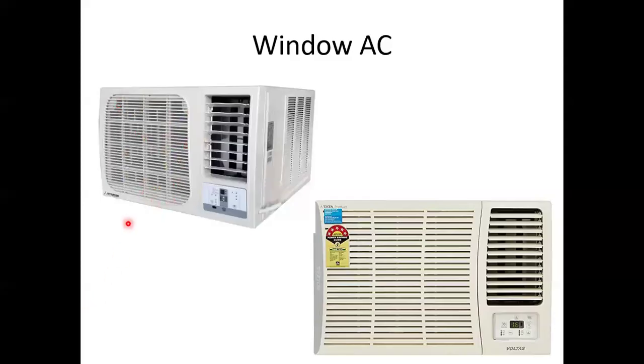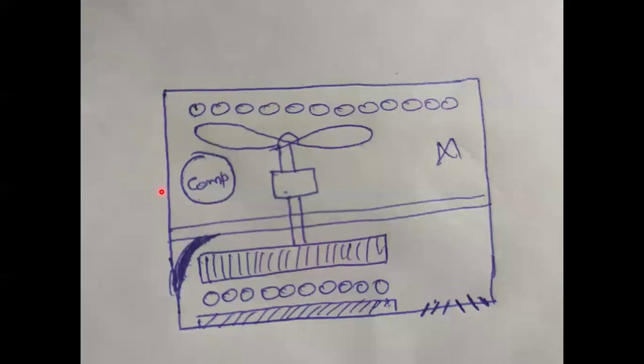Now, the room air will be entering this return path, and you will be having these air filters. Obviously there should be a 10 micron pre-filter. A small filtration takes place, and eventually this return air, I told you the specification of a return air is meant to be hot and humid. That means moisture content will be there. So this hot and moist air will be contacting the evaporator coil itself. You can see this now. This is the return air part. It should again contact the evaporator coil and be supplied to this side itself.